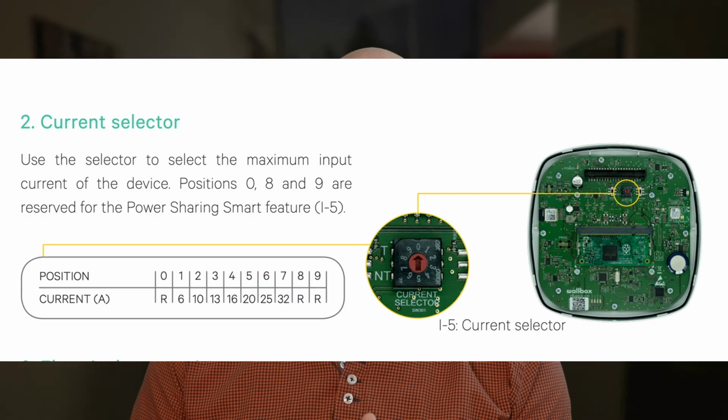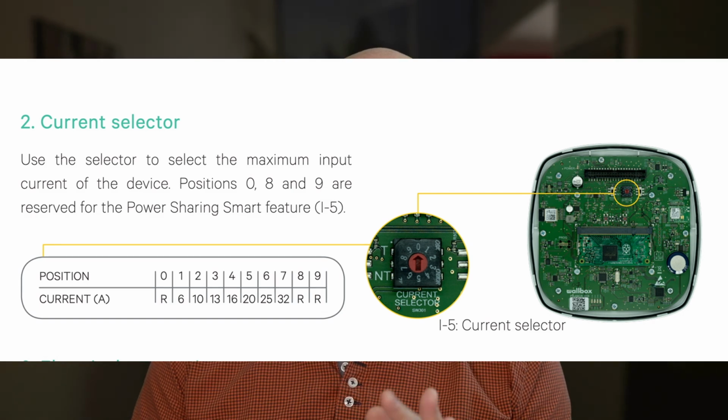I wrote to them that the information on the web was misleading, but they told me that they were comfortable with it. They can control it down from 1.4 if I connect it with one phase, and up to 22 kilowatts if I connect it with 3 phases, and I can choose between the two at the time of installation. So they're fine. And there is a dip switch where you can limit the maximum current to 32 amperes or 16 amperes or other values.